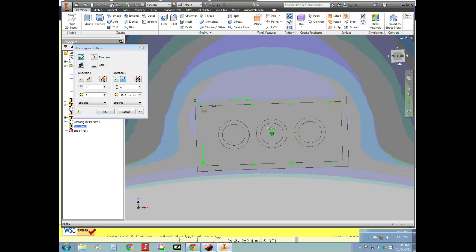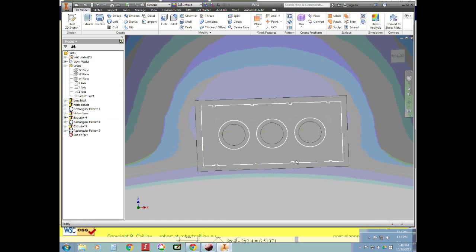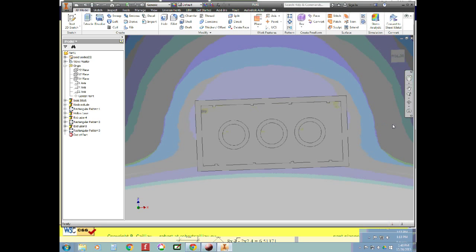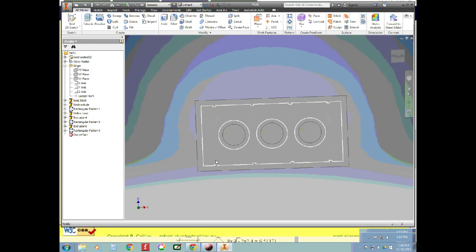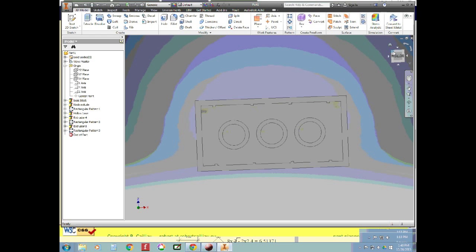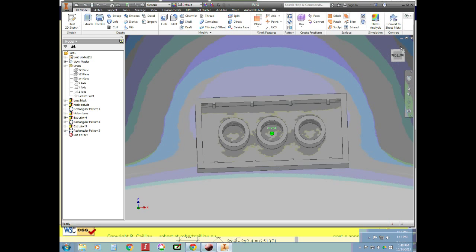And if you notice, it's still on the outside. We also need to subtract the thickness of that extruded feature, and that was minus 0.3. And yep, so we got to go back in here, minus 0.3, and should be good. Let's see what we get. Go ahead and click OK, and we have them. So once again, we did the distance across here, subtracted the wall thicknesses, and then the thickness of that extruded piece itself. We rotate, we can see those pretty well.